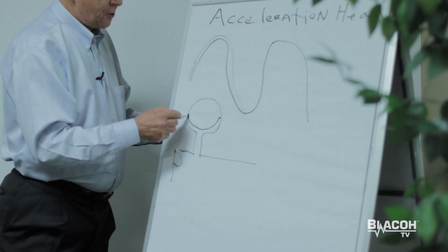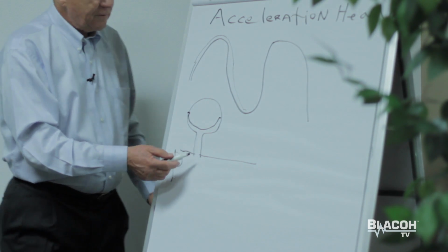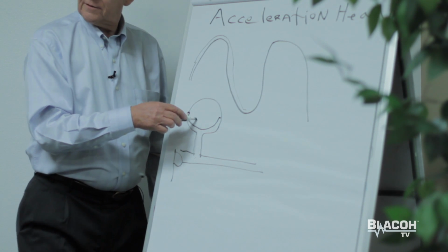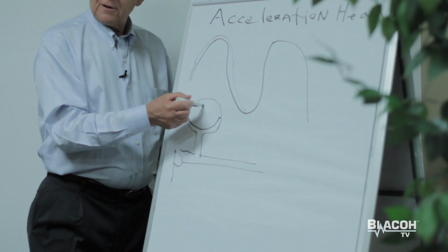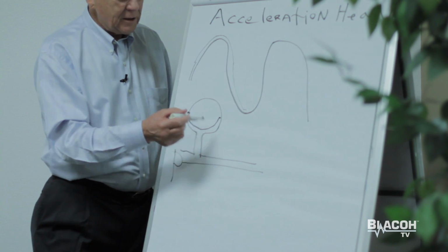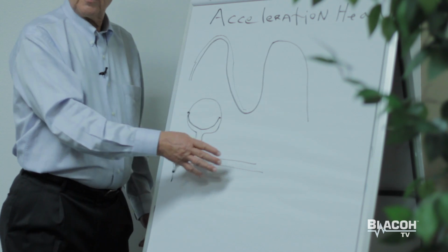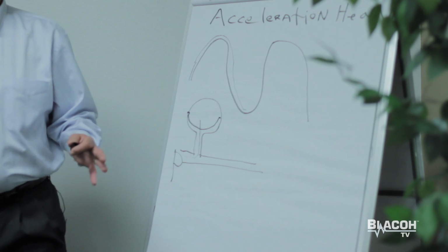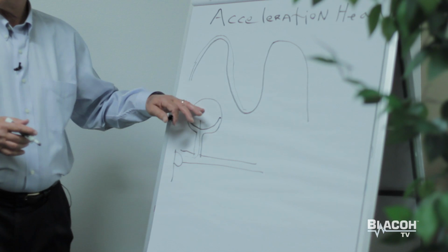on the discharge stroke of the pump, a certain amount of liquid goes up and is accumulated into the dampener. Remember, there's a gas charge on the top side of the dampener, but it's always at a lower pressure than the system pressure. So a certain amount of liquid goes up into the dampener. Now that takes some energy to push up against this resistance.